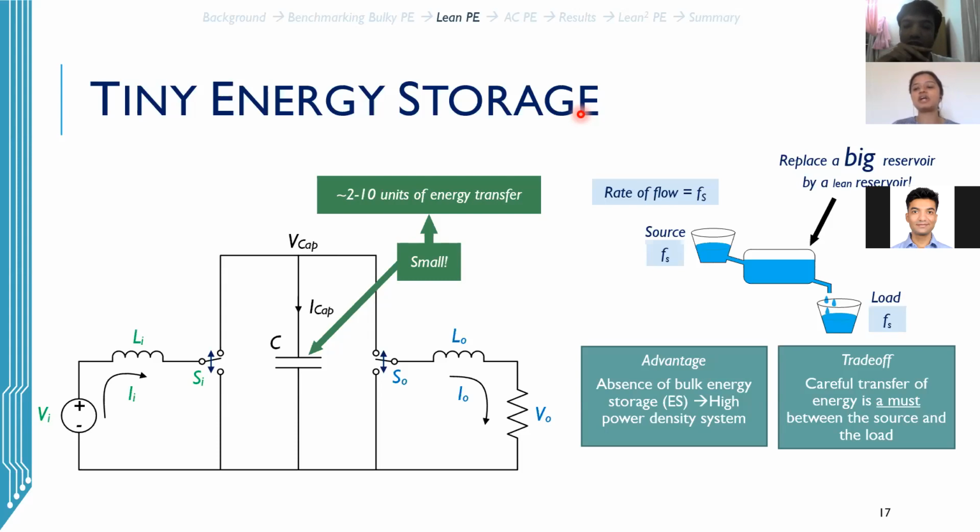Definitely when we are looking at other applications, there may be situations of fault ride-through conditions or where the source goes away, what happens? So such application specific situations need to be taken care of. And then the capacitor size may have to be increased because of the constraints which are put by the application.